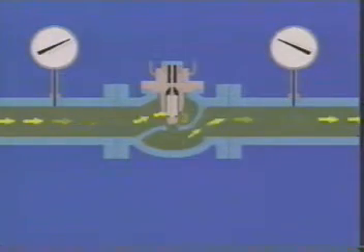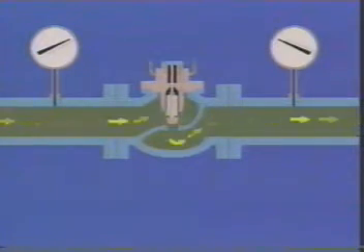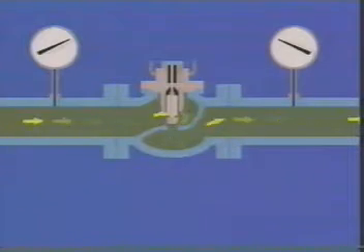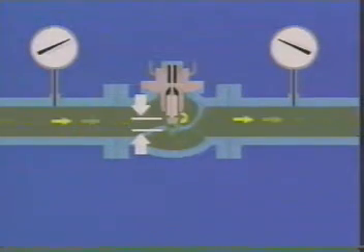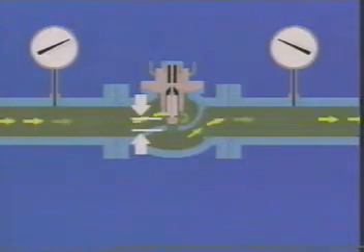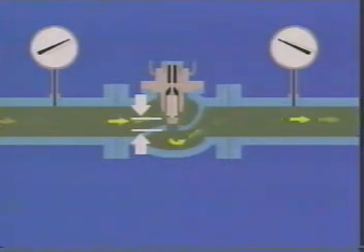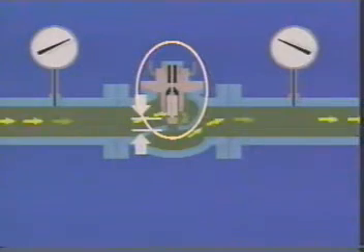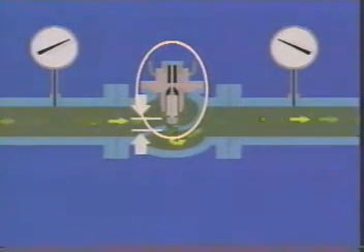Obviously, a larger orifice will allow more flow, and a smaller orifice less. A control valve acts as a variable orifice in a flow stream. The more the valve is open, the more flow it will allow through its orifice. But for a given opening of a control valve and a given pressure drop across it, the flow rate through the valve, that is, the valve capacity, is a function of the design of the valve trim.